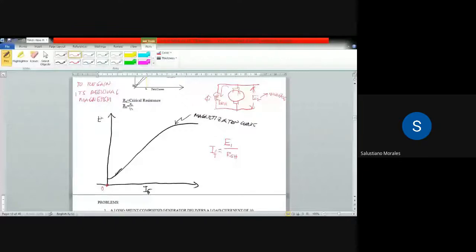then divided by the resistance of the shunt field including the field rheostat. So, assuming that the voltage E1 is this one, you can assume any value that is above the residual voltage. So, we have the residual voltage here, and there should be a corresponding field current, say IF1. Okay, so assuming that the resulting field current for that given voltage should be this value IF1.